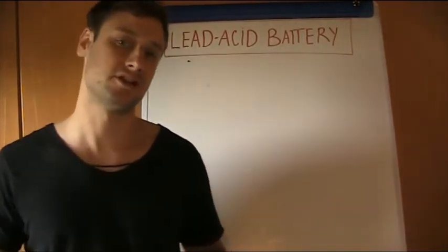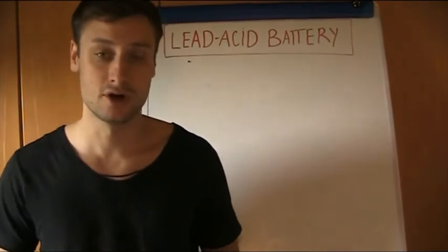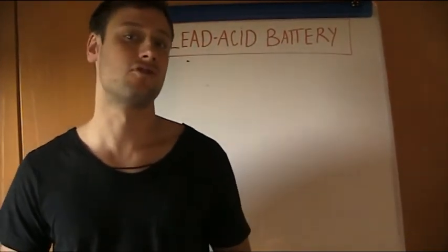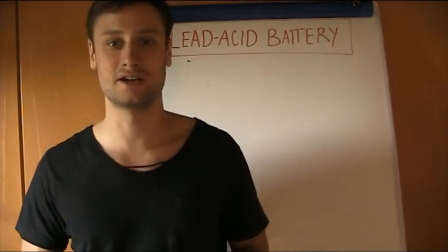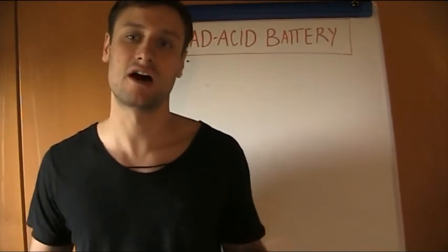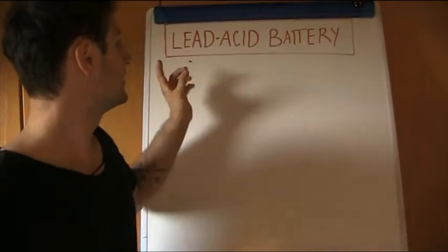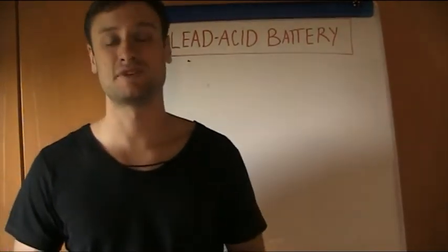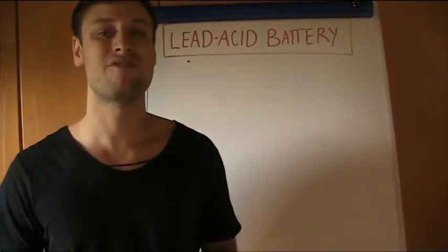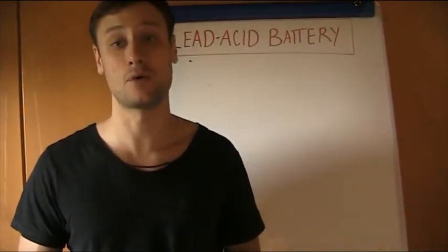To start a vehicle's motor, we need a large current, so it's important to have something that can provide this current value. Lead-acid batteries can do that, because even if the specific energy is quite poor, we have a relatively high specific power.